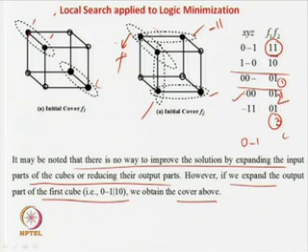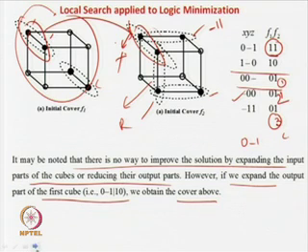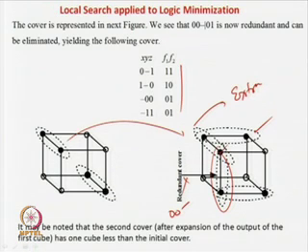And these things are there, but now you can think that for these two and these two, both of the functions are 1. So, you borrowed this guy from here to here, and then you can say that this one becomes a redundant cover and remove it, and you can get a better solution. But there is no elimination over here, this more or less remains the same. Here there is no optimization, only in terms of F2 there is an optimization. So, for finding the neighboring solution in this case, it was not just about removing one literal, but rather doing some export and import from each other. So, that is what is being done. It is being moved from here to here, and then you can remove this as the cover. Here it remains the same as the old solution, that is these two will be there, but we could have saved something in the F2 business.